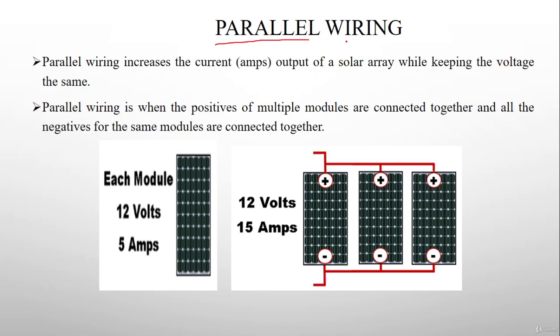Now, in the next example, we are going to talk about what will happen when we connect the panels in the parallel wiring or parallel combination. Parallel combination simply means that if we are taking 2 or 3 solar panels, the positive of each panel we combine by one wire, and the negative of each panel we combine by another wire. So simply we are collecting the terminals of each and every solar panel. The same terminals we connect with the help of the pre-assembled PV wire. That is the main difference between the series and parallel wiring connection whenever we join the solar panels in solar home systems.